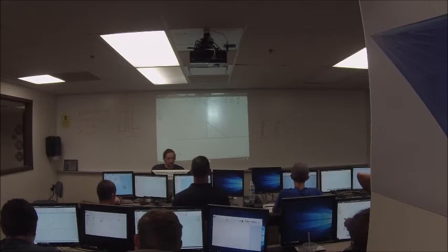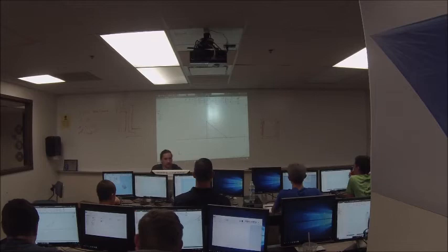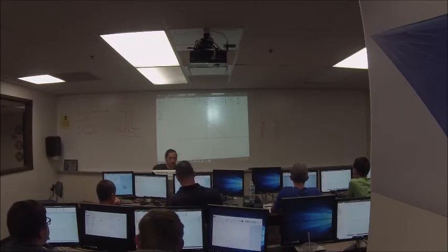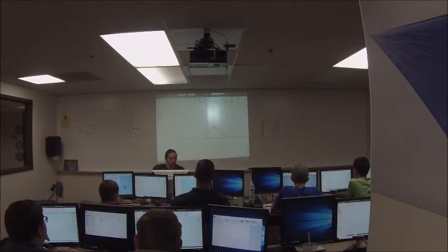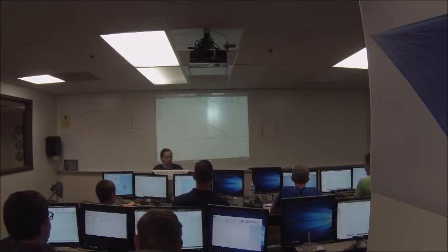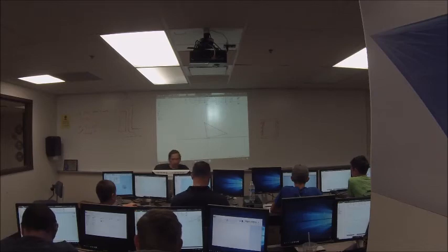So now you can see, well, I've got to hide the constraints. For instance, I can't click and drag on stuff right now because it wants to grab corners and other things. So you can press F9 to hide the constraints again. You can see now this line isn't vertical anymore, but it's still perpendicular, and I don't want it to be perpendicular. I want this line to be horizontal and this line to be at a weird angle. So I press F8 again to show the constraints, left click on the constraint I want to delete, right click and hit delete.